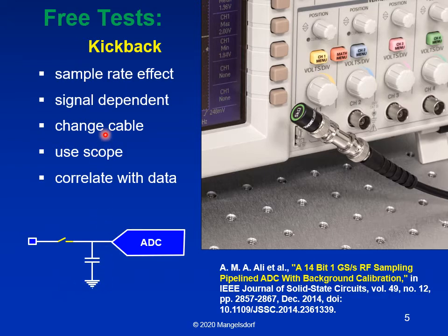One of the quickest things to do is just to change the cable. Particularly if you're working with cheap cables, you can get a lot of reflections bouncing back and forth in there. The next easy thing you can do is just replace the signal source with the oscilloscope and see what is being kicked out. This is assuming that the DC value at the scope will be appropriate.